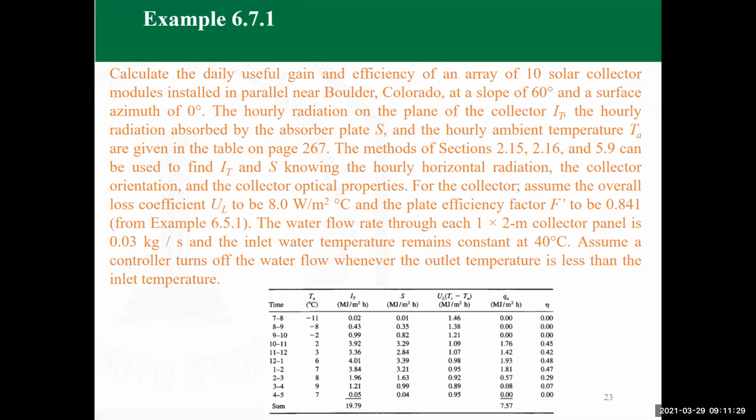So you may have controls of the solar collector that would allow turning on the pumps, for example, if the ambient temperature is above a certain value, which means that the sun has risen enough in the sky and it started heating, and accordingly we can account for this as some sort of control which can be done easily on the solar collector.